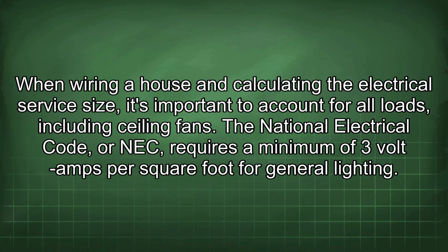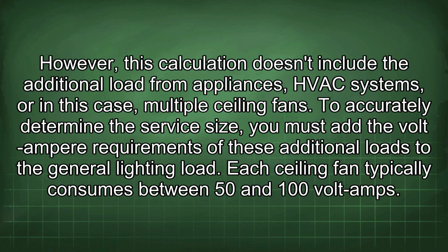When wiring a house and calculating the electrical service size, it's important to account for all loads, including ceiling fans. The National Electrical Code, or NEC, requires a minimum of 3 volt-amps per square foot for general lighting. However, this calculation doesn't include the additional load from appliances, HVAC systems, or in this case, multiple ceiling fans. To accurately determine the service size, you must add the volt-ampere requirements of these additional loads to the general lighting